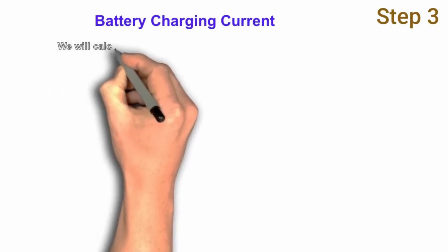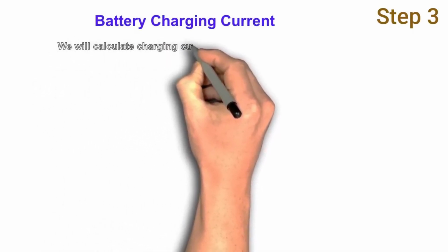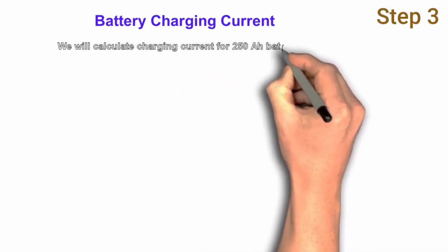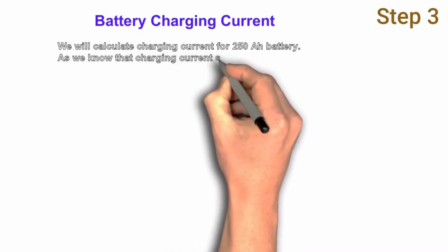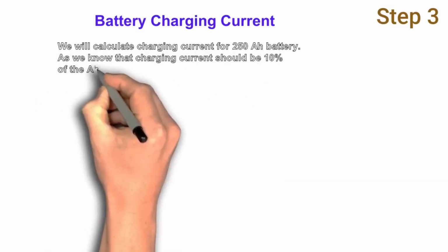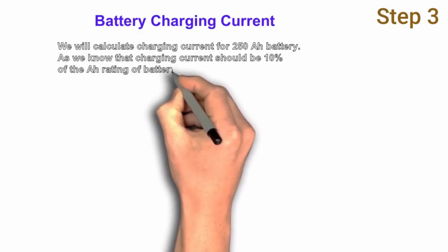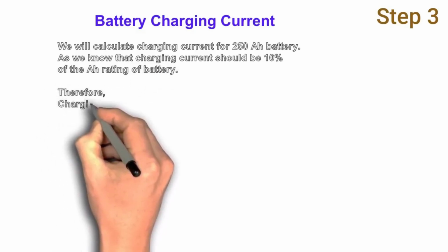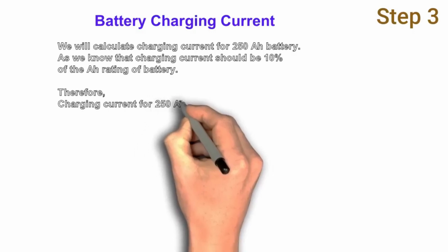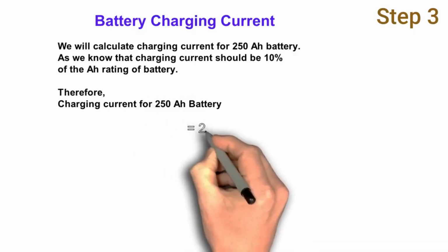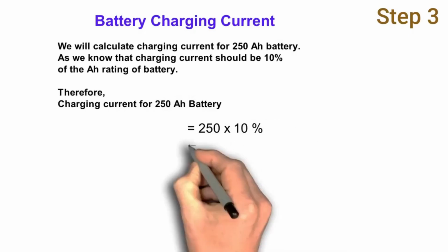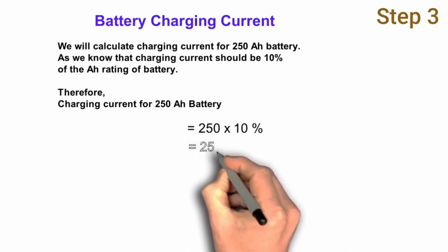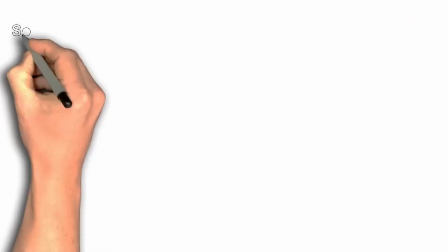Next, let's calculate the solar panel quantity. To determine how many solar panels you'll need, take your daily energy consumption and divide it by the energy produced by each panel per day. For example, if you consume 10 kWh per day and each panel produces 1.2 kWh per day, you would need approximately 8 to 9 solar panels. However, it's always a good idea to overestimate slightly and install a few extra panels to ensure you can meet your energy needs, especially if the weather is less sunny than expected.